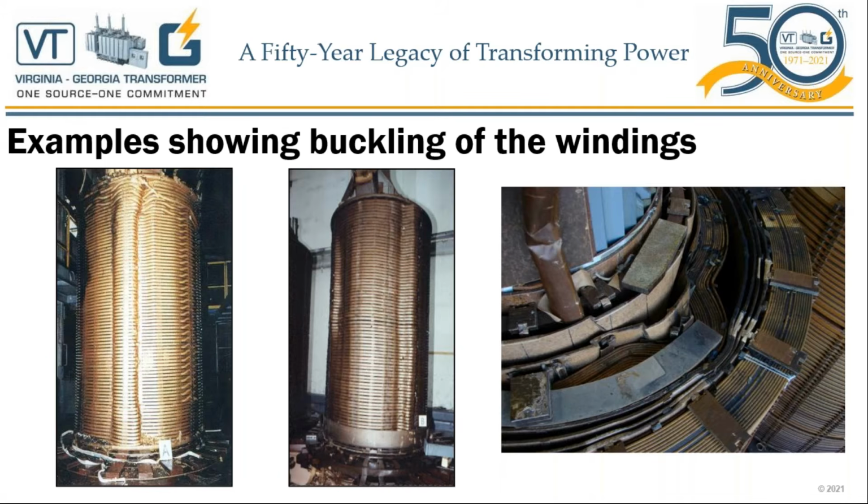The inner windings, we designed them to be self-supportive as long as they are manufactured tight around the core steel. What if the manufacturer of this winding did not produce a good tight winding? So please pay attention here to what I connected with what I said earlier. There is design, there are materials, and there are manufacturing practices that can all fail a transformer.